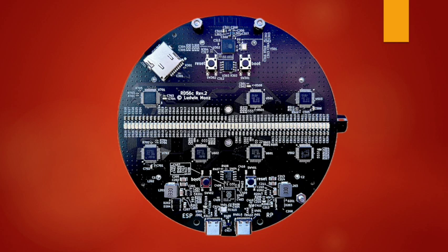In the upper half of the board you can see an ESP32-S3 microcontroller with a printed antenna for the Wi-Fi connection and a micro SD card reader. The controller is used as a web server and generates a website via which the display can be controlled. It can also download data from the internet to show it on the display. One example is weather data.